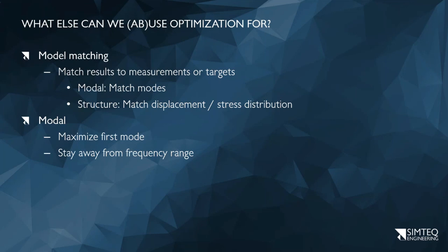That's normal, two-pole, as an example, a single phase motor. For something like that, we don't want any components attached to it to have a natural frequency close to 50 Hertz, because we expect excitation to possibly excite, and if it does, strongly excite that specific frequency.